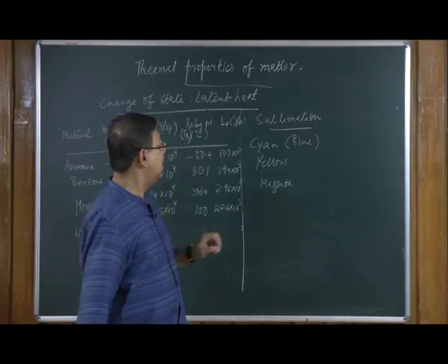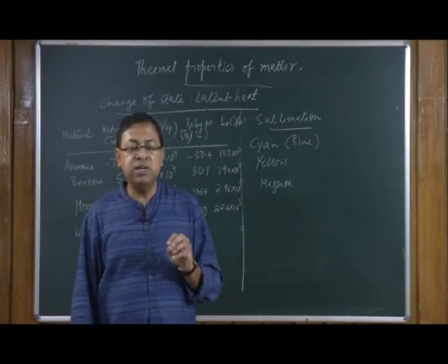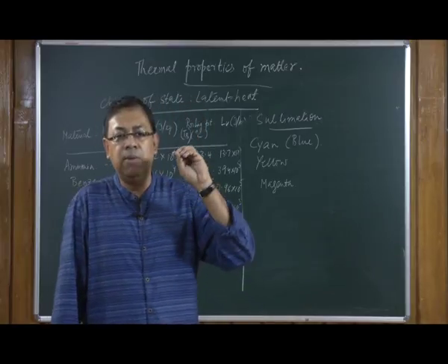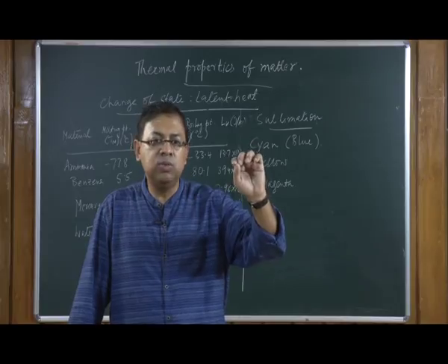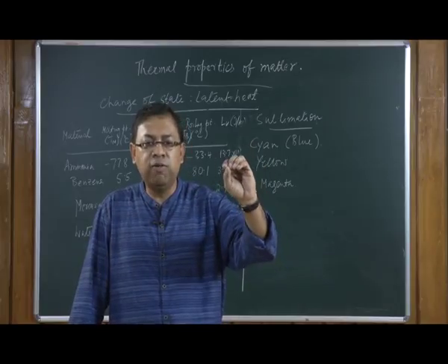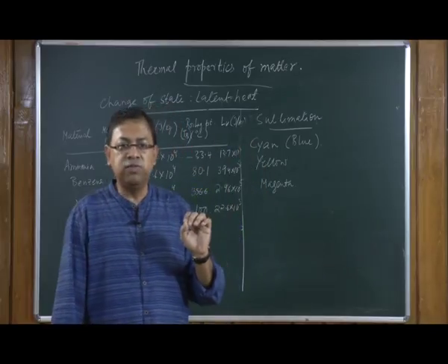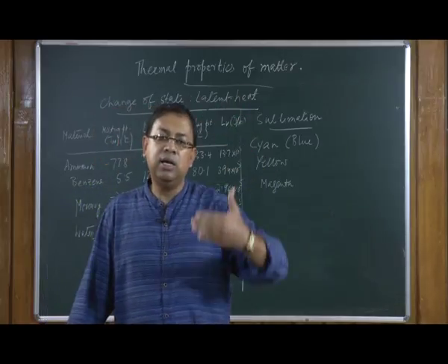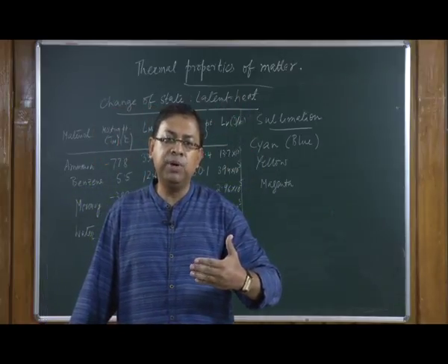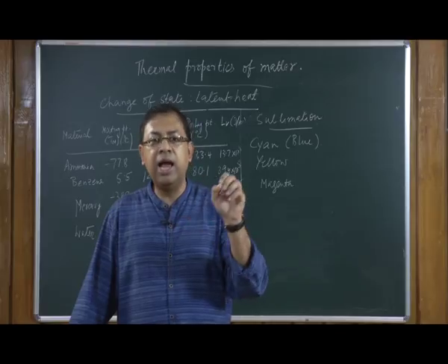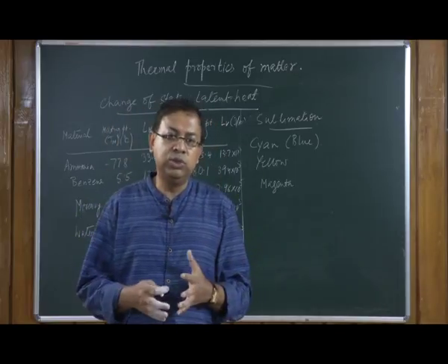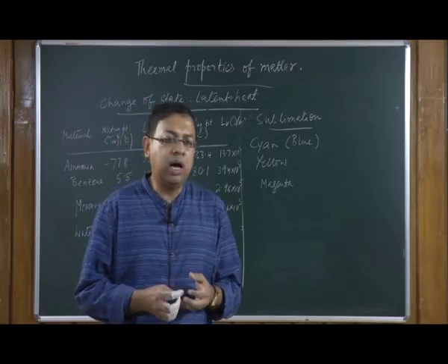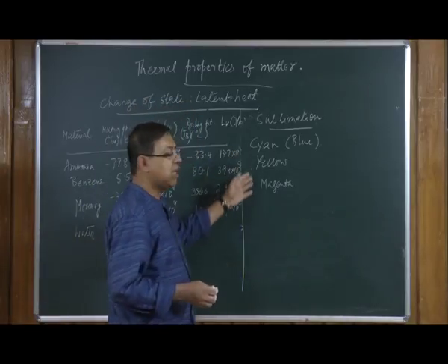So, this printer head has a heating element, which directly converts the pigments, which are the colors, in solid form to a gaseous form, and there is a coating on the paper which absorbs this and makes a mark. So, all other colors that you see in a color printout are combinations of these colors.